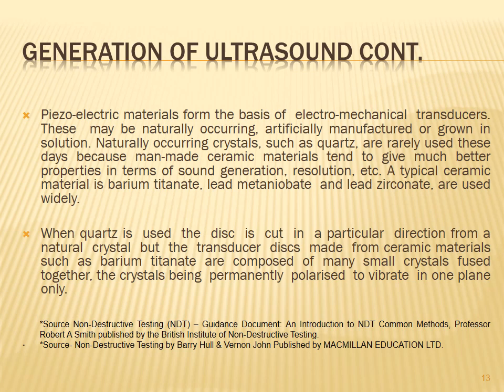Nowadays we are using man-made ceramic materials, but previously we used quartz, because the properties of man-made ceramic materials are better compared to quartz. The better properties are in terms of sound generation and resolution. Typical ceramic materials such as barium titanate, lead metaniobate, and lead zirconate are widely used nowadays.